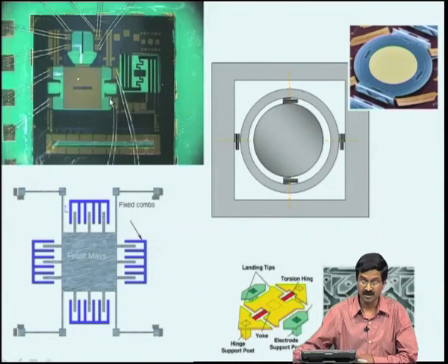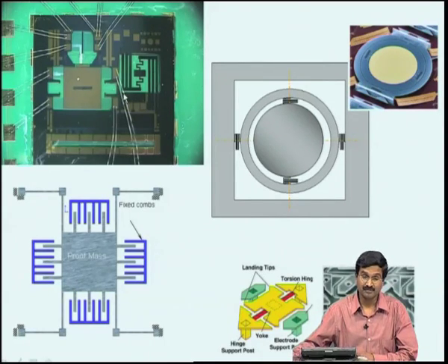At what frequency do they vibrate, what is their frequency response, what is their time constant, and how much time do they take to reach steady state? And if it is a sensor such as the accelerometer, what is the bandwidth of that sensor, what is the response time of that sensor, and many such questions.